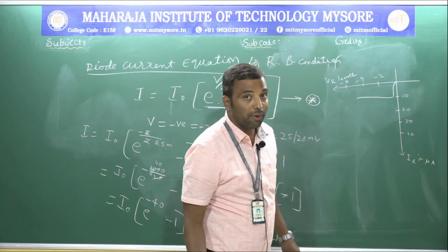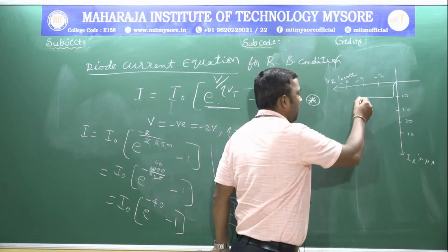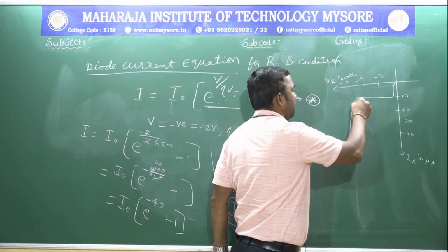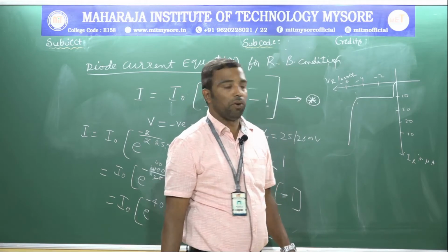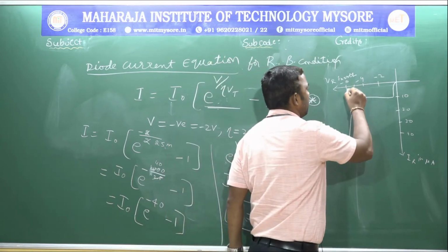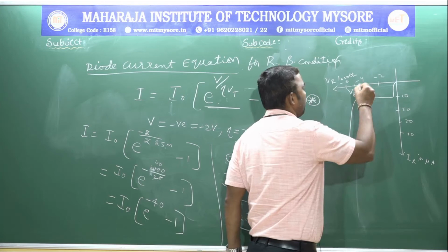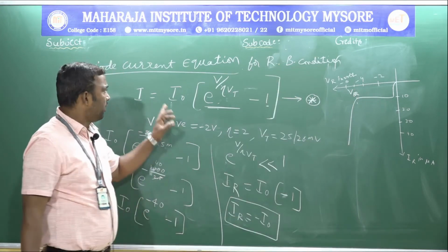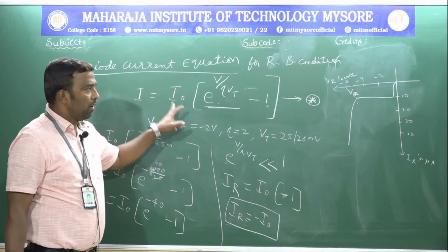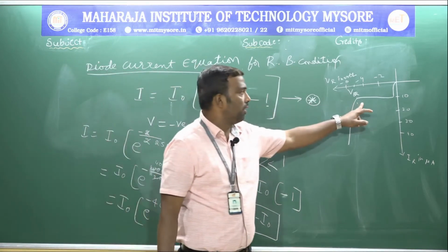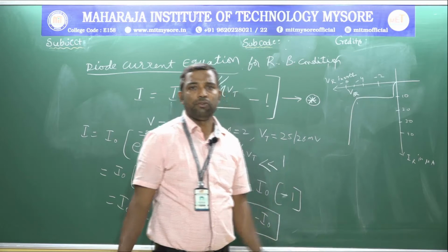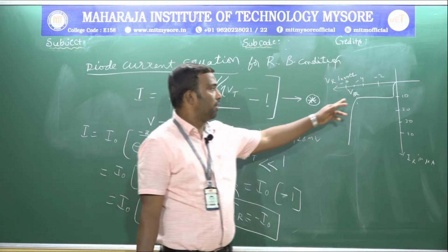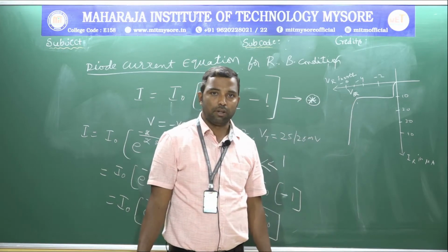If you increase the reverse bias voltage further, the current suddenly increases, which leads to damaging the diode. This voltage is the breakdown voltage VBR. In reverse bias the current is constant throughout the voltage, and increasing beyond the rating will damage the circuit.